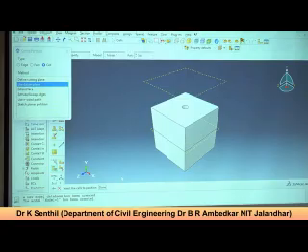Now the second approach: you model the 5 meter depth soil separately and the remaining bottom layers separately, like clay and sandy soil. Then you assemble it all together and define the interaction properties. The general contact may work very well, because if you go to the site, these layers are different. I don't think all 3 layers work homogeneously. It's not at all homogeneous. So you have to define the interactions.